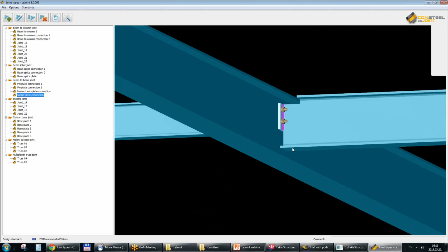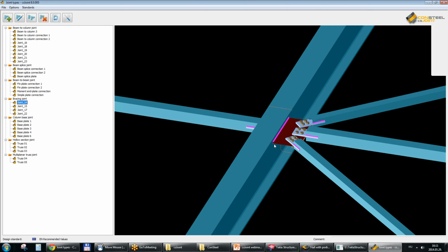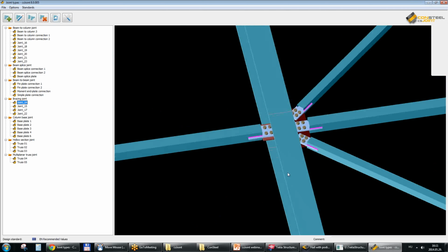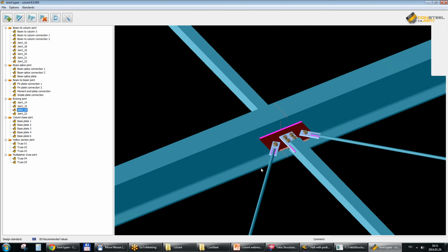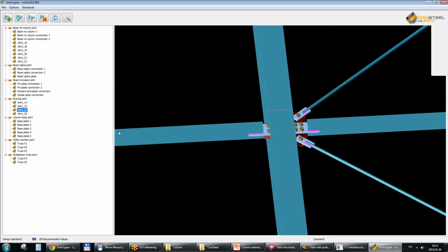And we have several bracing types, connections placed usually on a gusset plate, including these splice plate connections for hollow sections, or with tension bars, I bars. So these are some bracing possibilities.